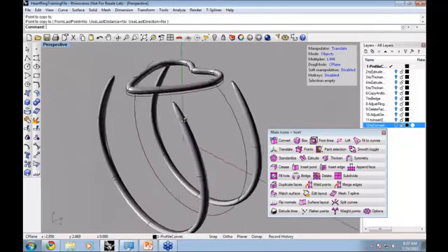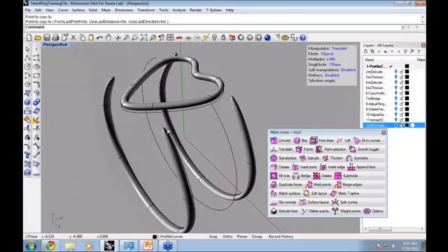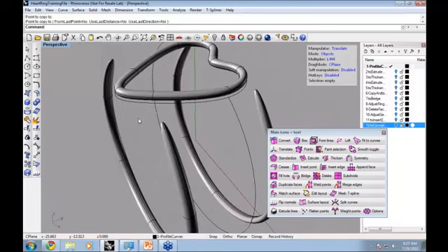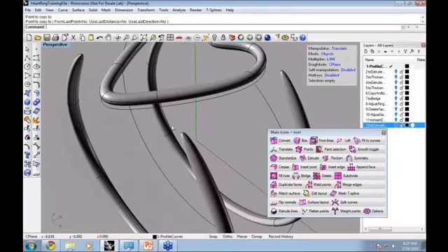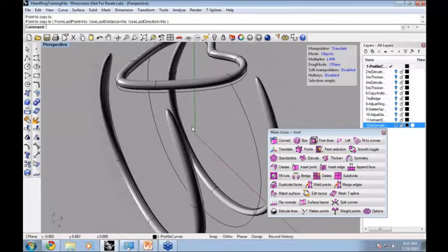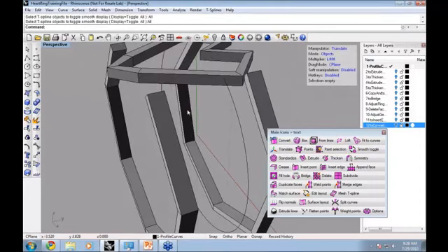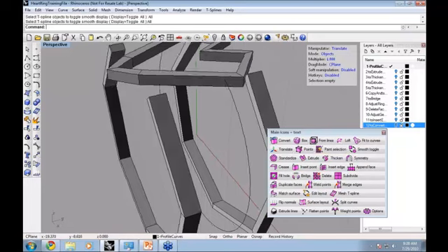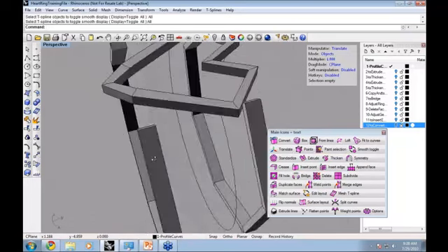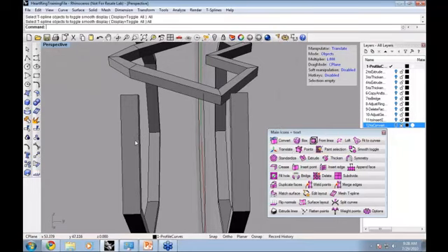So now that these are in position, I'm going to use the bridge command to bridge these together. One thing, the bridge command works on edges or faces, and you can see my faces are small and skinny here, and frankly hard to see. So when we're doing commands that require us to use edges or faces and they're hard to make out, I like to use the T-Spline smooth toggle, and I'll just toggle everything. This gives me a boxy representation of what the T-Spline's topology looks like, and it makes it a lot easier to see where all the faces are. And so I can do the bridge command, and it'll be easier to work.